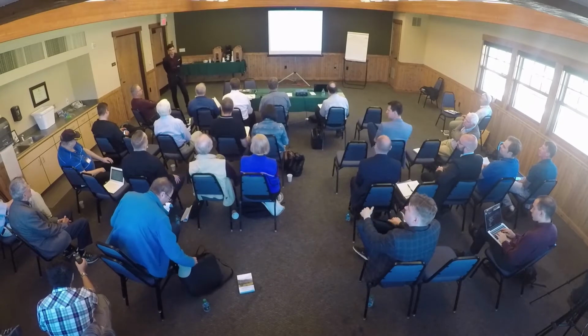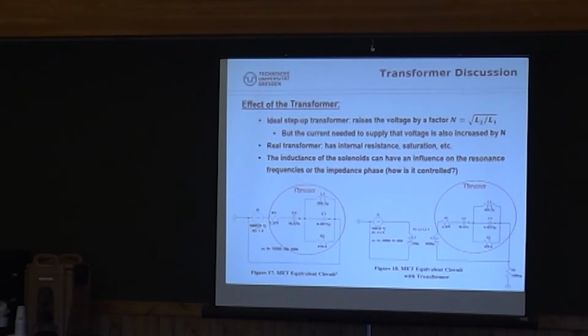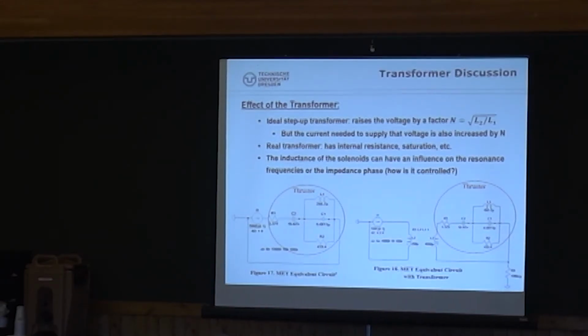What type of voltages are you talking about? 200 volt amplitude. So you guys have that naturally anyway, compared to 120 over here. No, he also used about 200 volt amplitude. Yeah. But about the impedance matching, it changes. It could change the impedance of the thruster. And the thing is that Professor Woodward's amplifier delivers power based on the impedance of the thruster. So that's the problem that we have. We don't know what power gets delivered to the thruster because there's no current measurement.